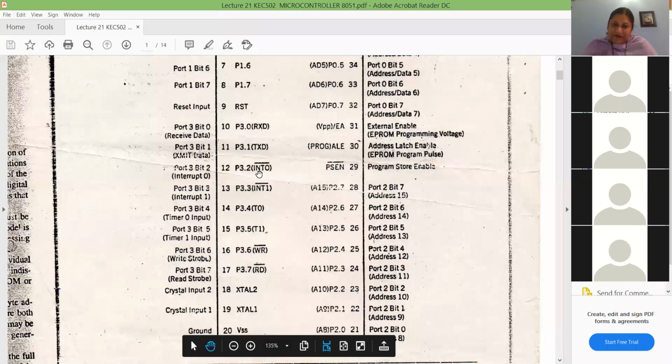And in 8085, when you connect 8255, ports are completely input or completely output, all 8 bits. But here in this case, each port pin can be assigned as input or output. So suppose you want to assign port 2 bit 7 pin as input, you can assign port 2 bit 6 pin as output.